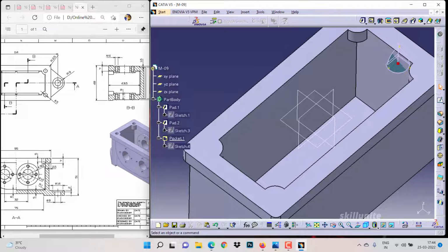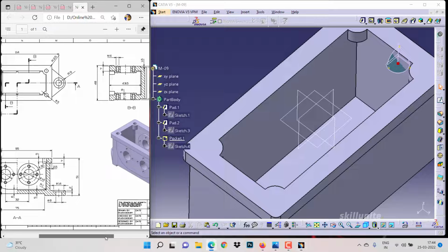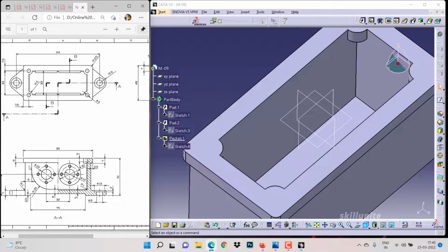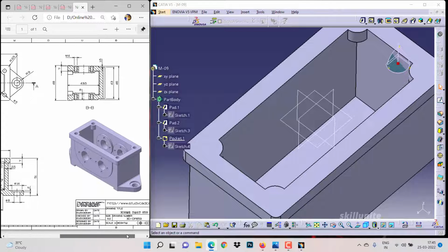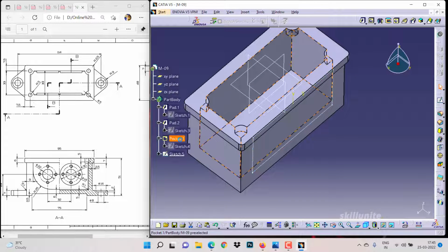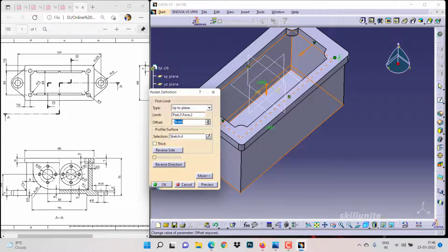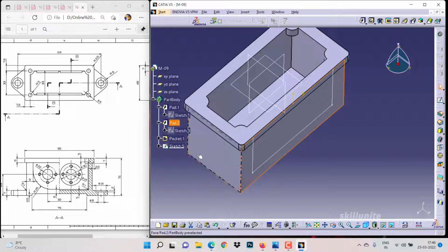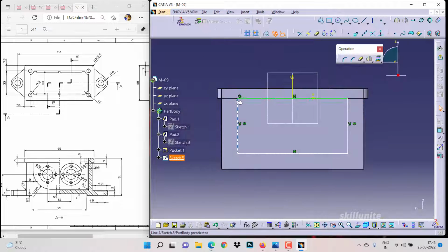As I told already, this has to go a little bit, 1 mm inward, so we will do it later. The next step is this extra projection, we have to do it. As you can notice, everything we are having, we will create in one direction, then we will mirror it in the other. Before this pocket we need to do the cutout, and only then make the pocket, because that extra 2.5 will be there. Maybe this one we will keep at minus 7.5. Then I'll select the side face, or open the sketch itself.